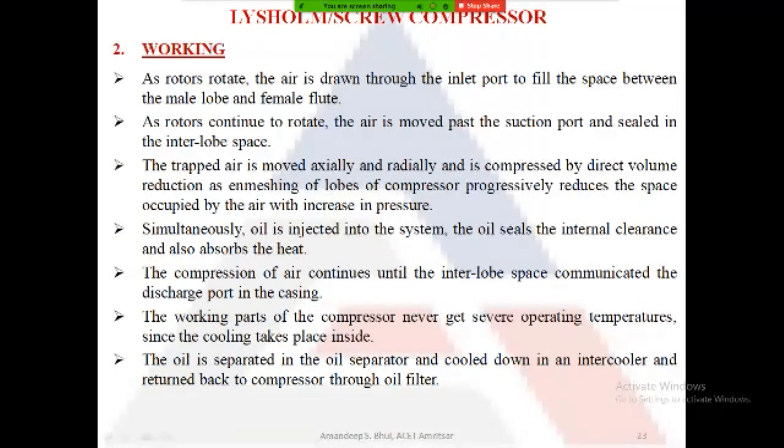So the trapped air moves in the axial direction, and also radially along the radius of the rotors, and it gets compressed by direct volume reduction, because the enmeshing of the lobes of the compressor progressively reduces the space occupied by the air.